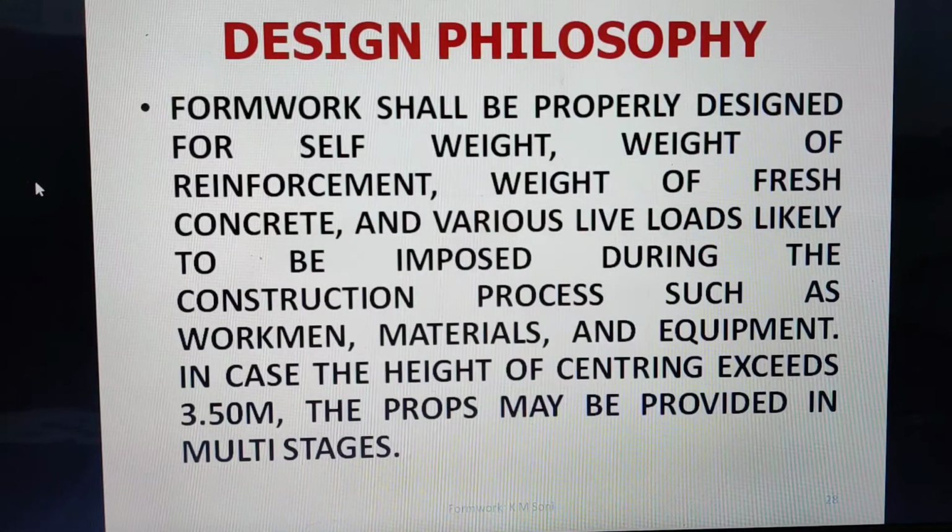And if we talk about the design philosophy of formwork, then because it is used with green concrete, it has a lot of loadings. Formwork has to be properly designed for self-weight itself, weight of reinforcement, weight of fresh concrete, and various live loads likely to be imposed during the construction process, as workers will be there, workmen will be there, materials will be there, equipment will be there.